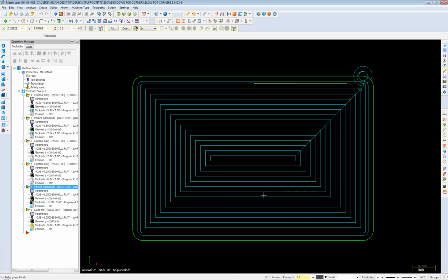Jimmy asking, should you always simplify splines before running toolpaths? No, not necessarily. Mastercam is designed to cut splines. It just depends what you're doing. Generally, no. I simplify when I bring IGES files in, because IGES files a lot of times overcomplicate simple lines and arcs and actually create splines. That's when I suggest doing the simplify, compared to bringing in any kind of solid.